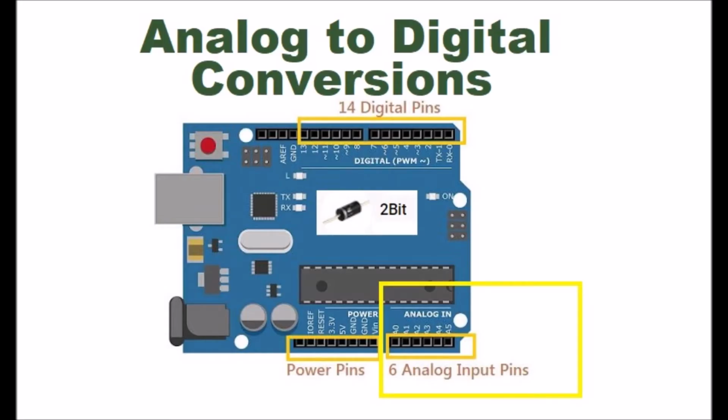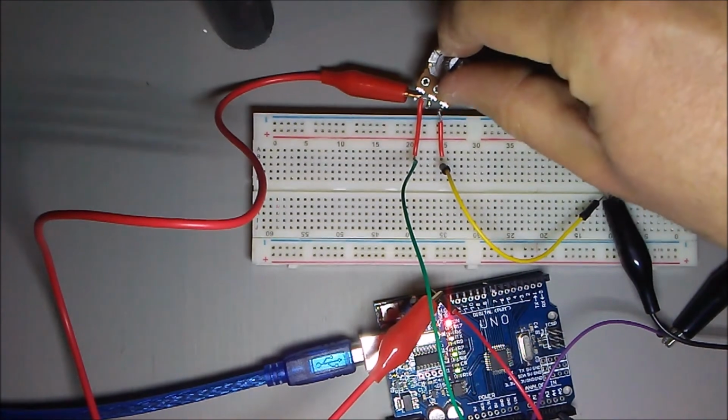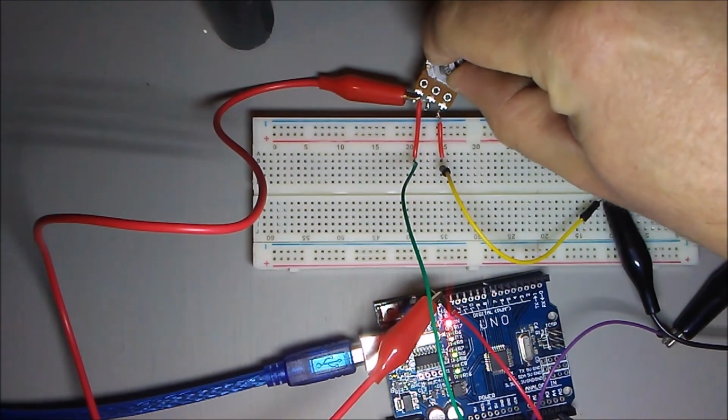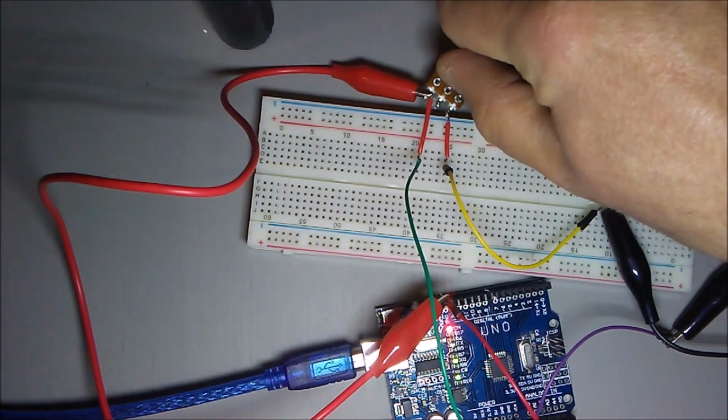You may already be aware the Arduino has analog pins. On the Uno, there are 6 from A0 to A5. These are made use of by a 6-channel ADC. The converter has 10-bit resolution, returning integers from 0 to 1023.